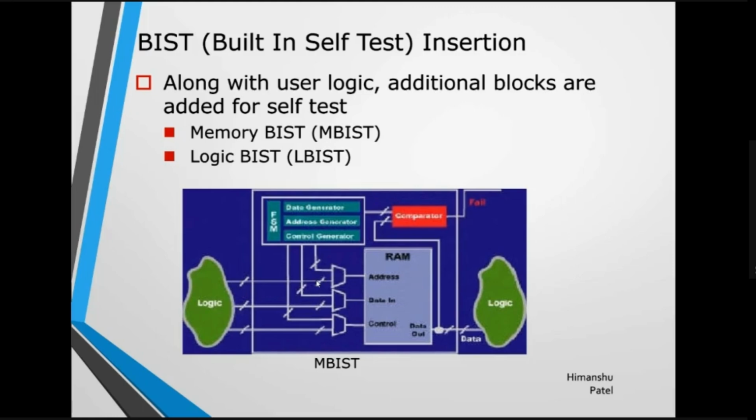You don't disturb that. It is the work of the RTL engineer to change the code at any point of time. So you as a DFT engineer add additional logic by adding muxes on all the logic that you want to test, either memory or logic, but you will not touch the functionality. There's a golden thumb rule of DFT: do not disturb the functionality.